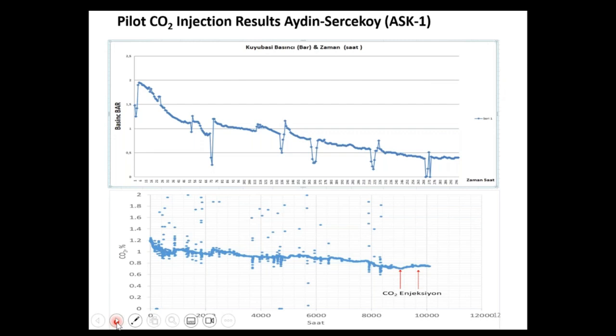neither brine. But in our case, if you see the first graph, when we started, it was around 2 bar, and then it came down. This well could actually take much more brine and much more NCG, but still 72 cubic meters per hour was re-injected at 2 bar. After a certain time, as you see, it's coming down since the downhole fluid mechanics and thermodynamics balance is coming